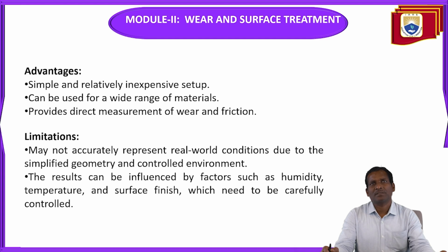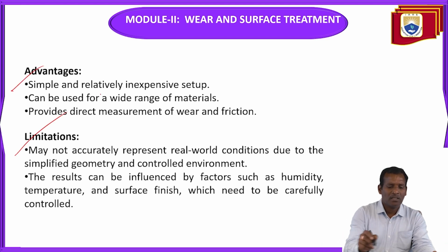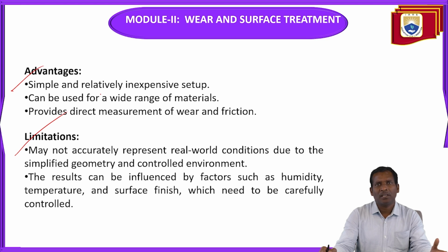What are the advantages? The advantages of the pin on disc test are a simple and relatively inexpensive setup, it can be used for a wide range of materials, and it provides direct measurement of wear and friction. The limitations are that it may not accurately represent real world conditions due to the simplified geometry and controlled environment.